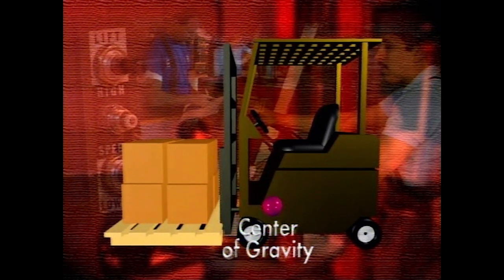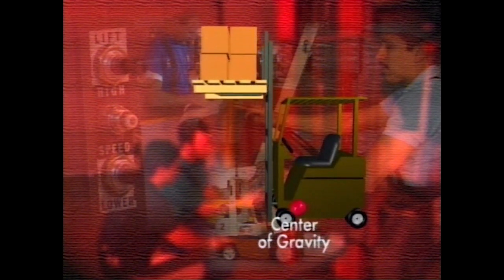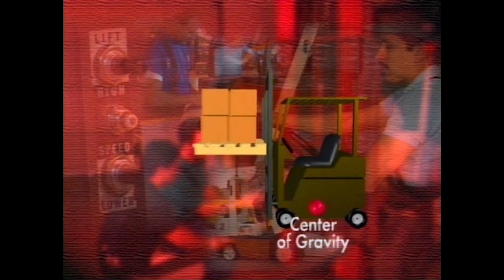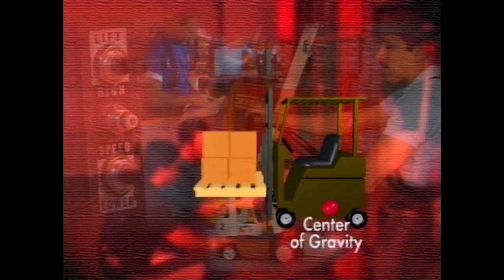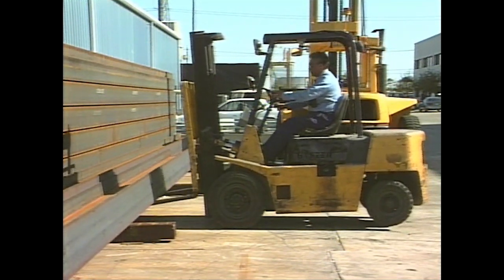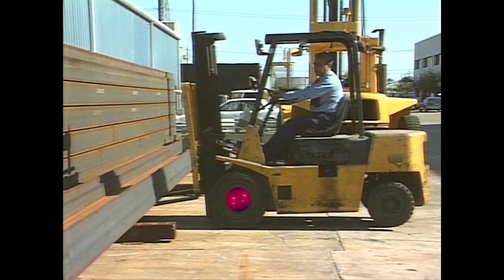Additionally, as you raise a load, the center of gravity shifts away from the truck and towards the forks. Forklift engineers designed the forklift with this in mind and calculated this center of gravity shift in determining the safe lifting capacities. When equipment operators exceed the safe lifting capacity and try to lift excessive loads, or if they have extended load centers and try to lift heavier loads, the center of gravity can be exceeded and the forklift will tip over towards the load.